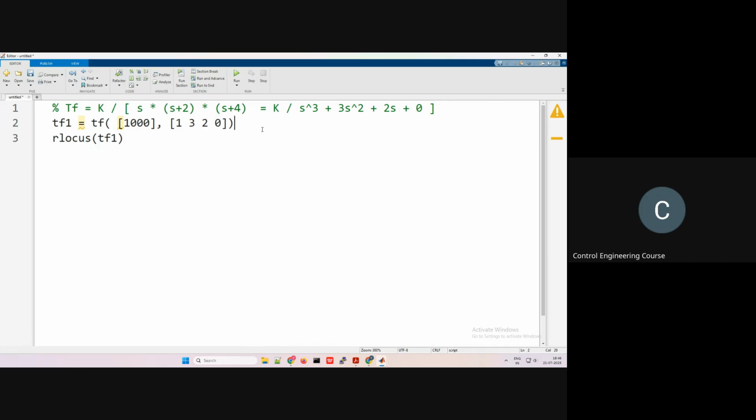Clear? So why do we need a compensator? So far we have changed the values of k to make the system respond in a desired way. So what if we add some poles or zeros? What if we couldn't make the system respond in a particular way only by changing the gains? We might need to add more poles or zeros. So how can we strategically add these poles and zeros to make the system work in a desired way? That's where the compensator comes into the picture.